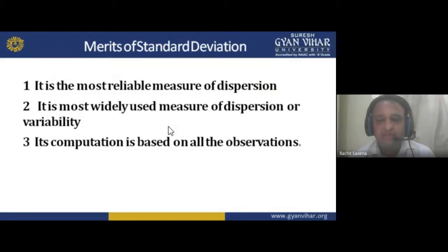They are near to 5: 4.6 for 4 times, 4.7 for 2 times, 6 readings. But in one reading I made an error. Due to parallax error I read only 2.5, where the main reading should be 5. I took the half reading, that is 2.5. So that is the error. But we can calculate, because the computation is based on all the observations. So one observation is my error.